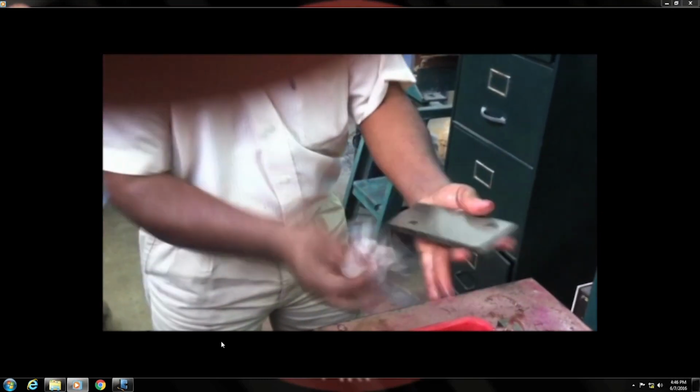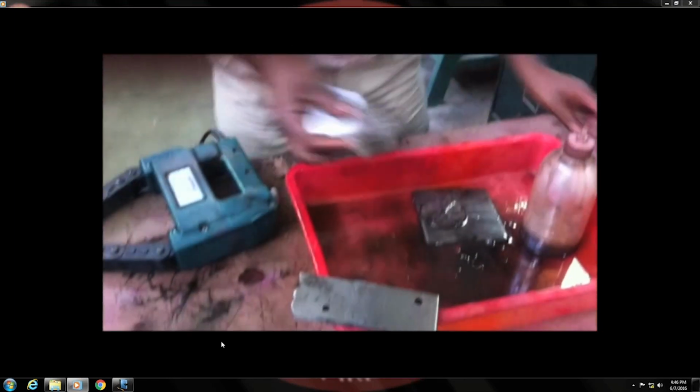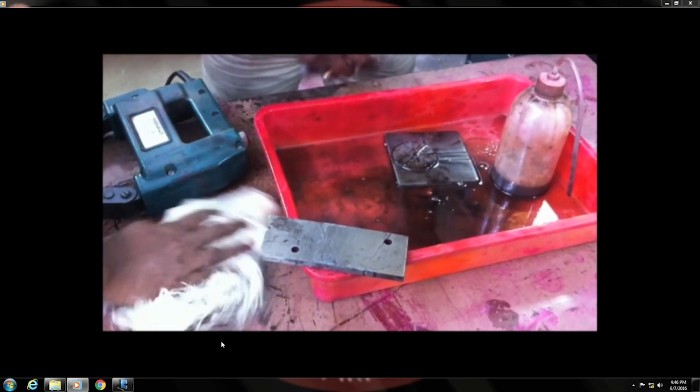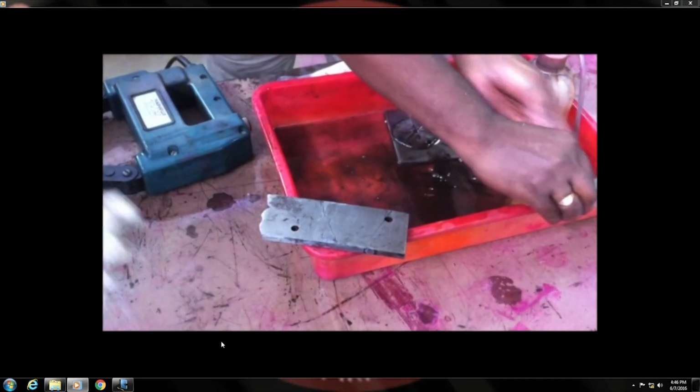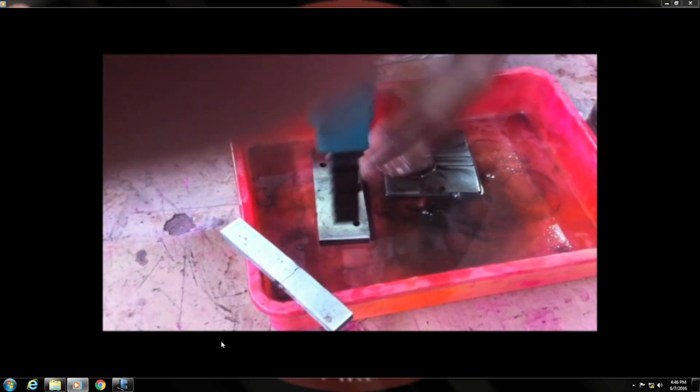Now, we will pick up some kind of part which we know is defective, and then we will show you how these surface flaws, surface defects are made visible by this magnetic particle testing. Okay. So, this is a piece of a steel plate. Some big cracks you could already see, but that is not our concern right now, because they are already visible by the naked eye. We want to see if there is something else which is not visible by the naked eye.